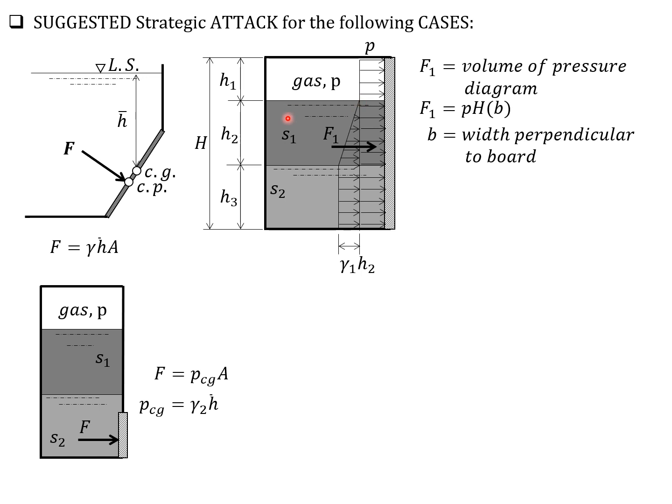Because this is liquid 1 and the depth or thickness is H2, the pressure at this interface is equal to P, pressure here, plus gamma of liquid 1 times H2. So the increased pressure here is gamma times H2 for this triangle because P is already here.